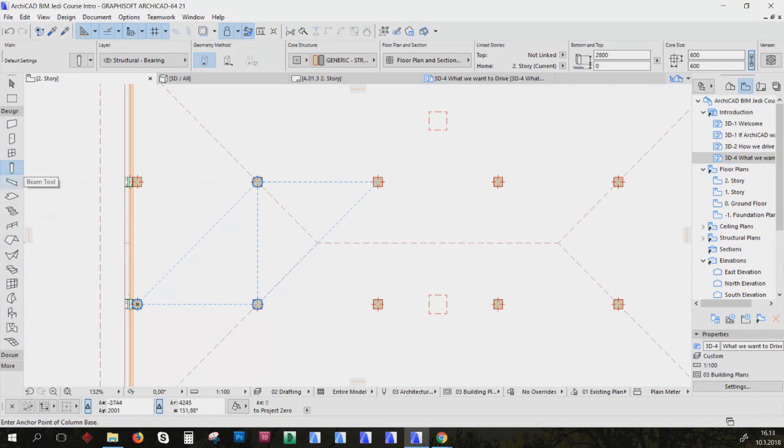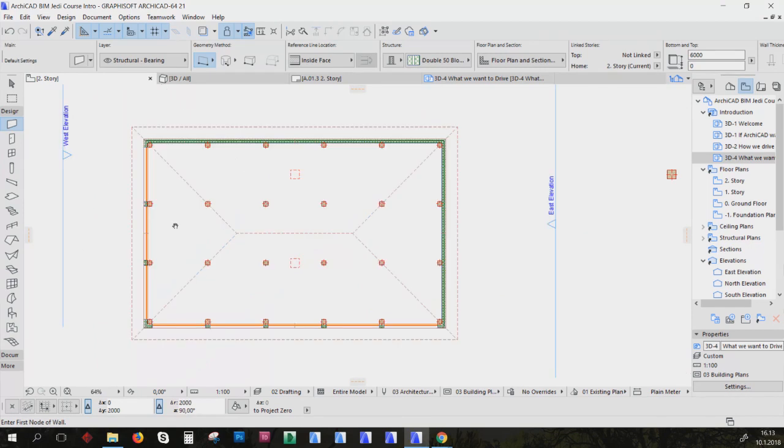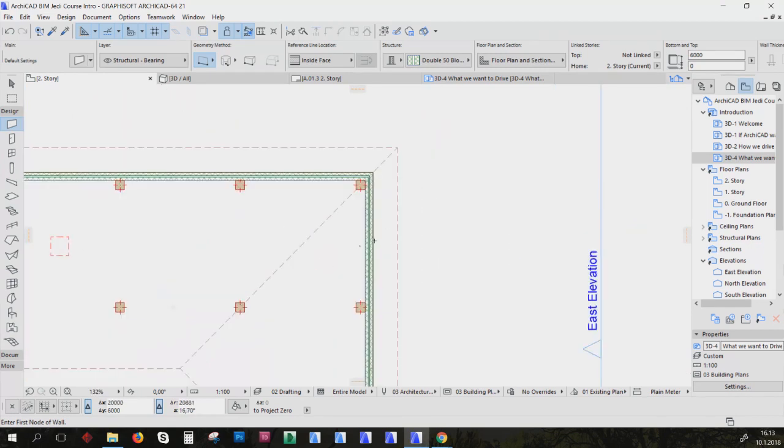Now if you were drawing a line or a wall, wall tool, and you wanted the wall to be a specific distance, turn gravity off. You can shift to lock it, and then X, say 5 meters, and it will stretch that wall to 5 meters from where you started.